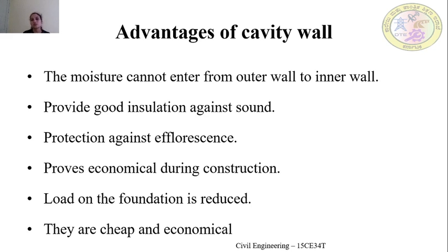That is one of the main advantages of the cavity wall. The next advantage is that it provides good insulation against sound. It also gives protection against efflorescence, it proves economical during construction, and load on the foundation is also reduced, and they are cheap and economical.